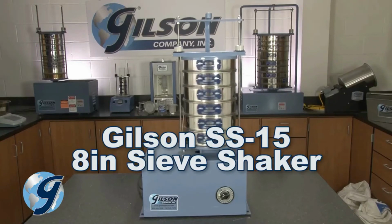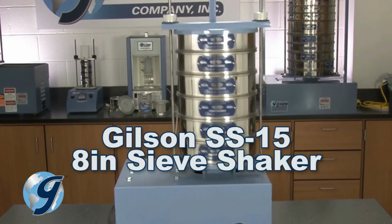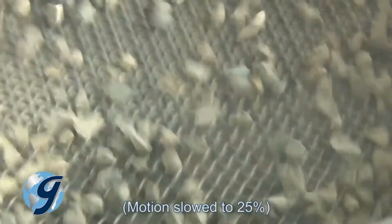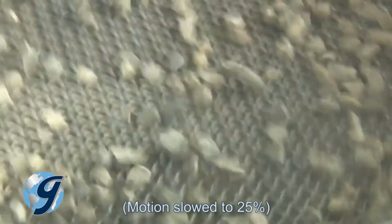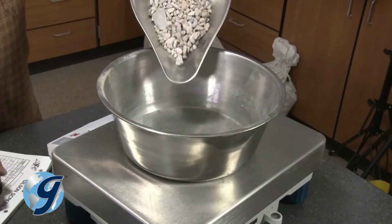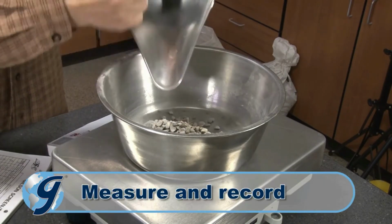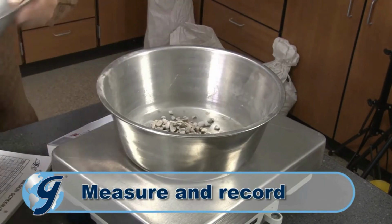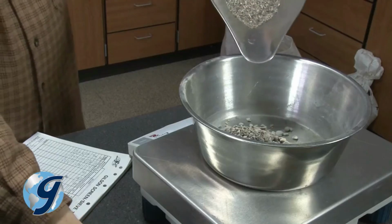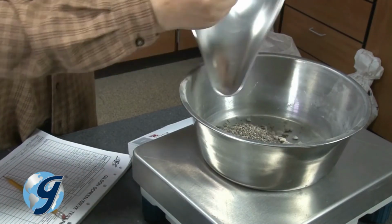The SS15 delivers superior accuracy and repeatability for particle separations by combining a back and forth lateral motion with an up and down and tilting motion, which causes test material to travel in an orbital direction on the sieve surface. Once sieving has completed its course, measure and record the mass weight of each sample size increment on a scale or balance to the nearest 0.1 gram. Repeat this process for each sieve and the sieve pan.